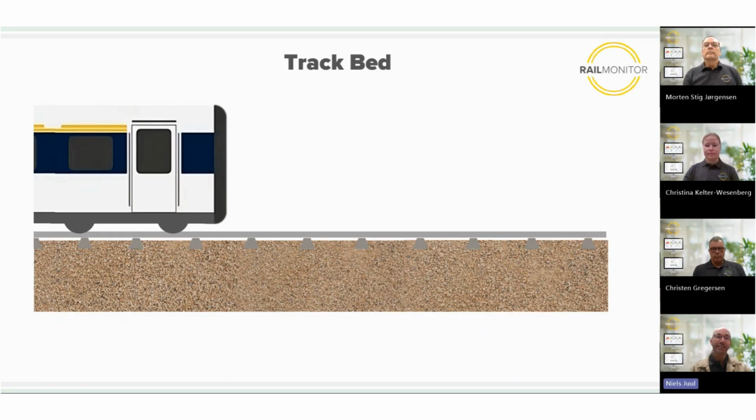Besides this, the track bed also helps with drainage, prevents track deformation, and absorbs vibration from the train movement. Due to its construction using ballast, the track is also able to move in a natural way vertically, and it is also able to absorb temperature changes, the load, and ground movements.